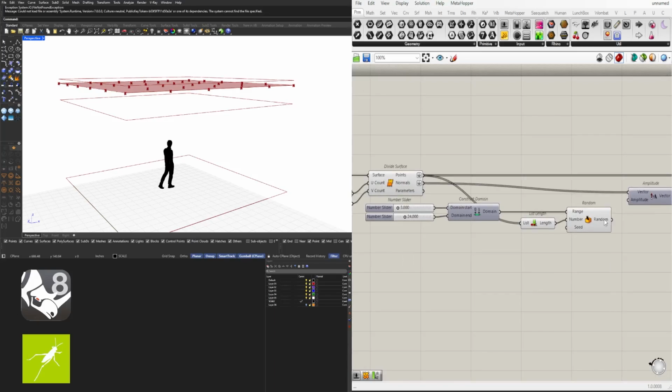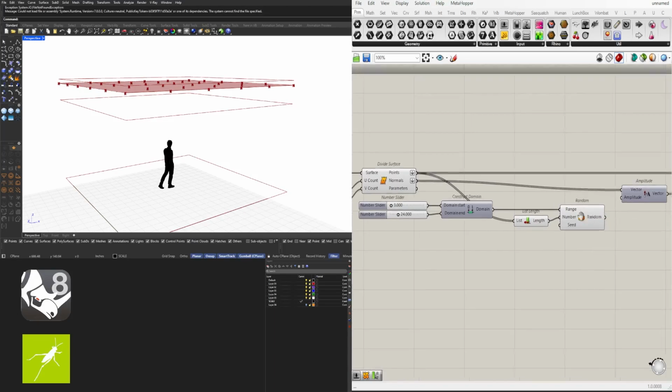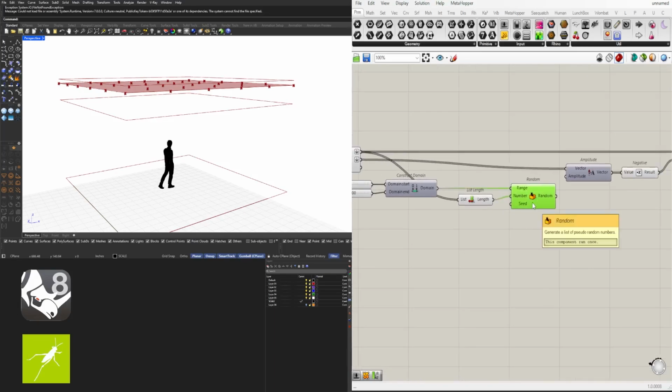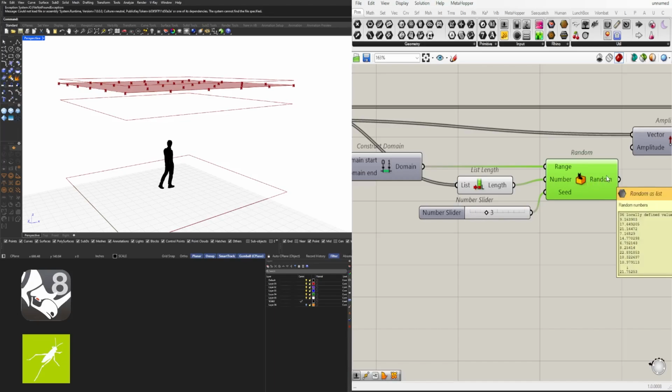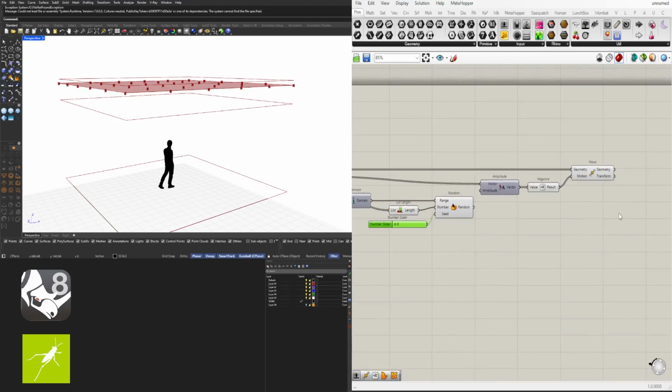And so this is just one iteration. If you think about it, when creating random numbers, you can actually have an infinite number of random sets created here. So to be able to control that, it has a seed, and by default it says 2. So we'll create a slider of 10. We'll set it at 0, and we'll say that seed of 0 creates these numbers, but notice that the first one is 18. Now, if we change this, the first one's going to be 9. So it'll just create random solutions to the random numbers.